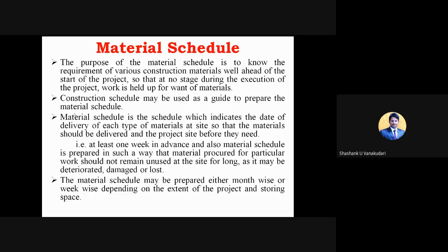The material schedule may be prepared either month wise or week wise, depending on the extent of the project and storing space. If you prepare it month wise, usually the quantity of the material will be larger than week wise.